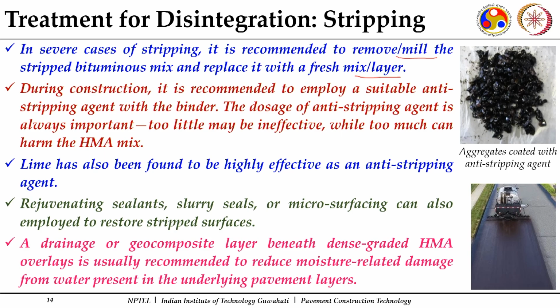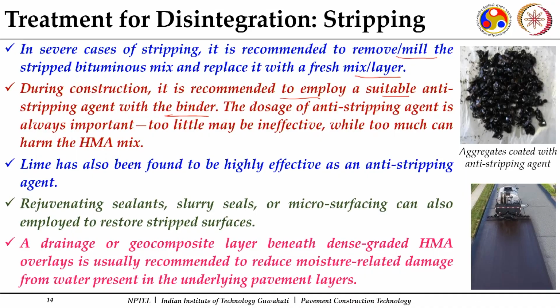It is no longer recommended to keep that particular mix. The one which has already stripped should be milled up and a fresh one laid. And during construction, it is always recommended to employ a suitable anti-stripping agent, because many aggregates are not good enough for stripping resistance. In that case, we can use a liquid anti-stripping agent.